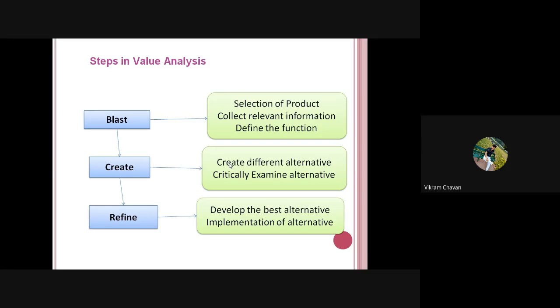Then if you want to increase the production, you can go ahead with the 4th axis VMC machine, or a 6th axis VMC machine also. In that case, your man-to-machine interaction will get reduced, and angular drilling can also happen in that particular 4th axis or 6th axis VMC machine.